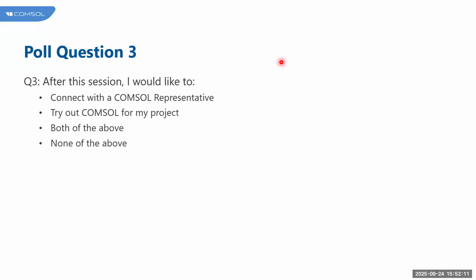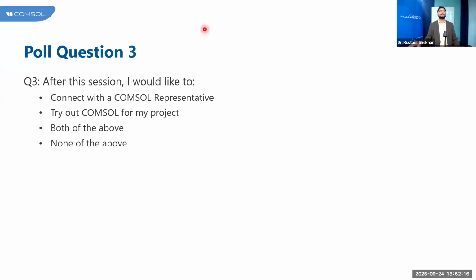One of the questions is, I am working with high temperature solid oxide proton exchange based electrolysis. Is this supported? Okay, so yes, if you are working on a high temperature proton based membrane electrolysis, this will be supported, and I can say that will be much simpler than the low temperature, because at low temperature you will deal with one more additional problem, which we call water flooding of the membrane. But at a high temperature, we don't have that kind of issue. So we can get rid of one issue.